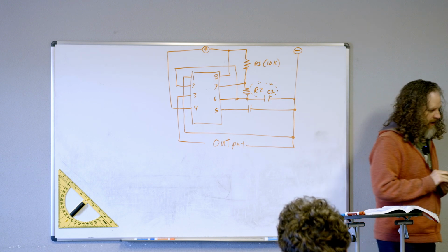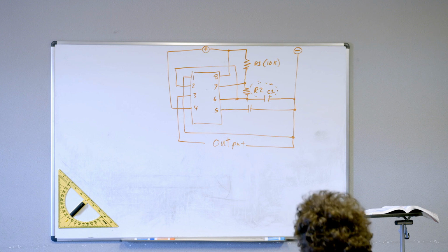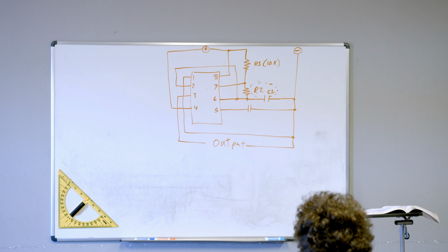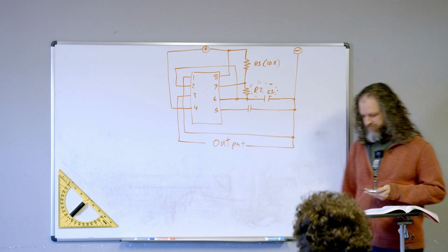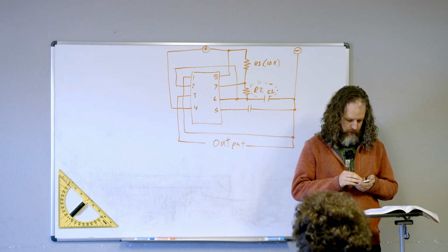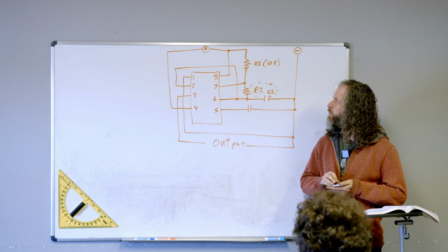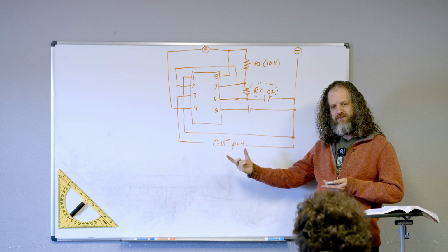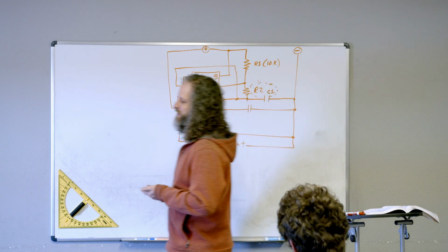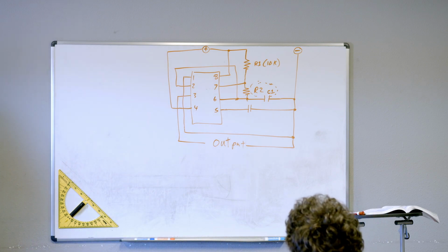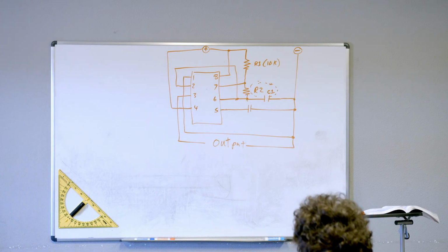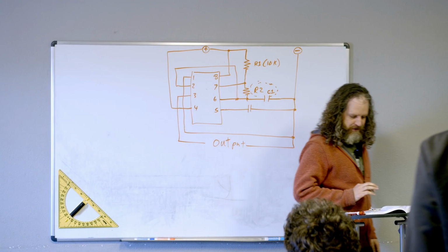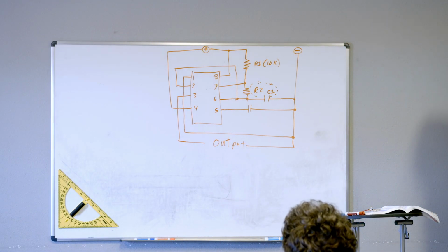If you get it fast enough to where the LED looks like it's just on, you're probably in a good place. What is this output? It's your LED or the oscilloscope or a buzzer. I would put an LED in there with a resistor so that you can see it for now. And then you can potentially try it with the oscilloscope and see what kind of things you can get.